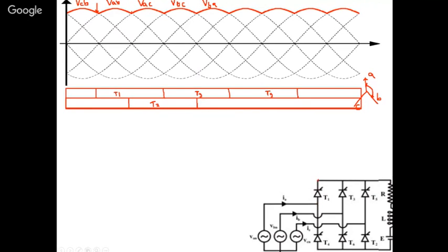How will the short happen? Say now T1 is on, okay, and similarly your T4 is also on. So at some instant, it may become a short also. Suppose your load is very low, think that your load is not proper, so there is a chance.